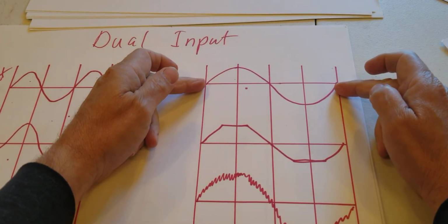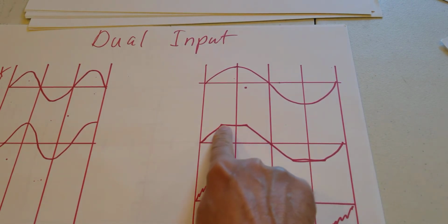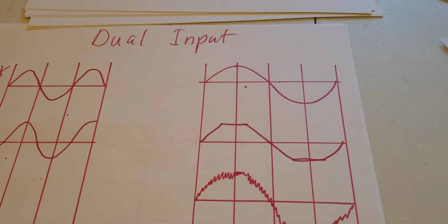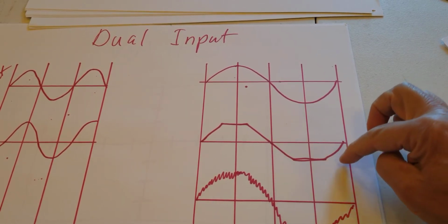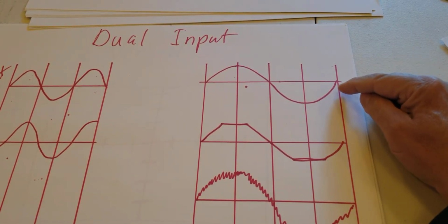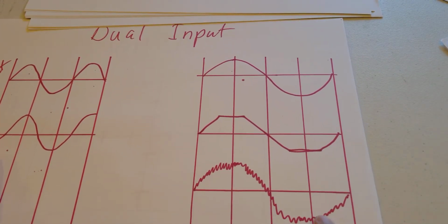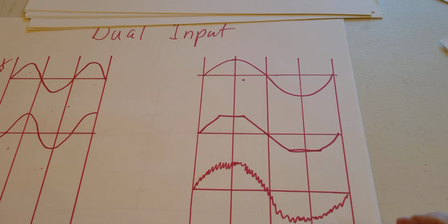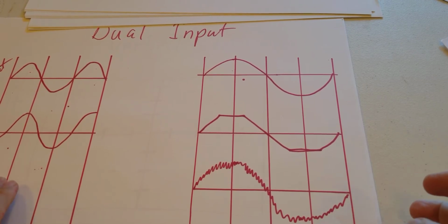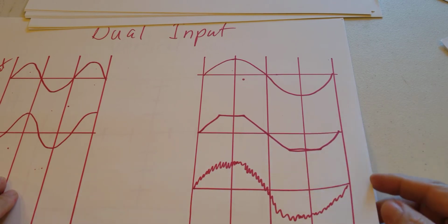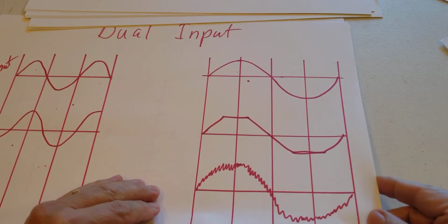The other issue with the dual input, like say if you had an input that looks like this, nice and clean, and then you get this little chop at the top and at the bottom, that's called harmonic distortion. If that was a sound system, it would sound terrible. So you could use this to troubleshoot. You say, well, my input looks perfectly fine, my output looks terrible. Or if your output looks like this, you'd say, look at all the noise. There's some kind of electrical interference, radio signal, the power supply, or a loose connection causing that. So it could be used for troubleshooting.